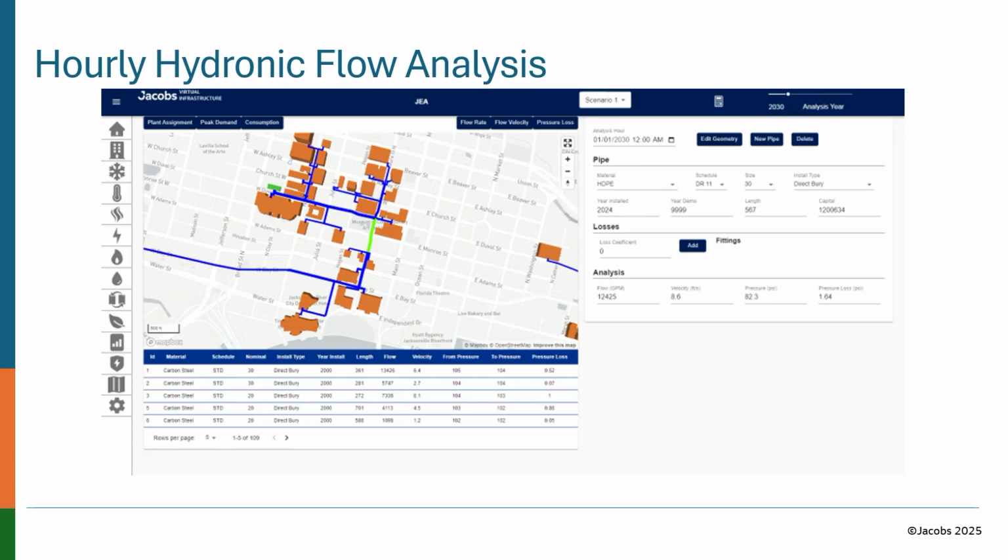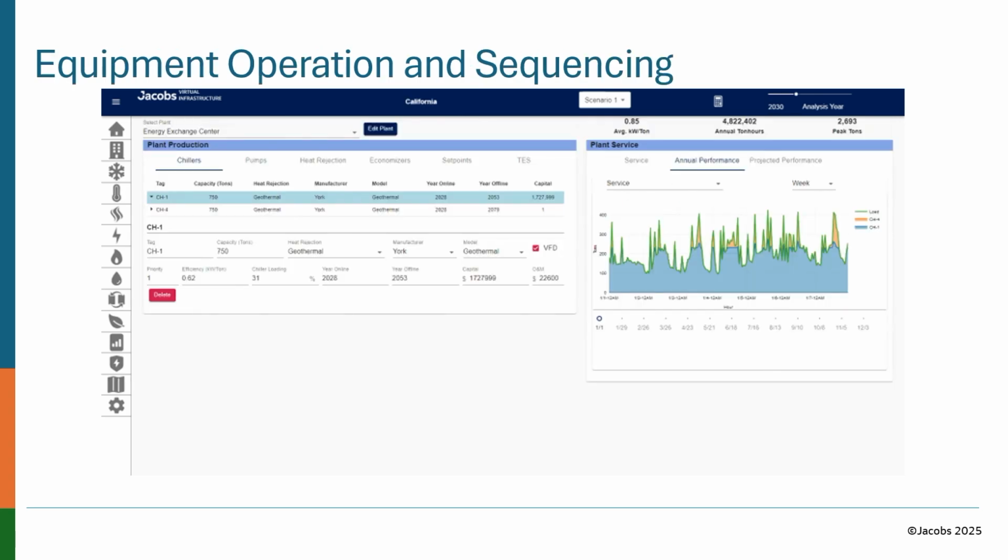We do flow modeling within the software as well. You can do it pipe flow, Fathom, whatever works for you, but we like to build it out here because, again, this software is built out year by year so that we can just draw out on a map and understand where the disturbances are going to be for our utilities or our clients, and just help understand where that resiliency is going to be maintained each year. If we need loop systems or mesh networks or what have you.